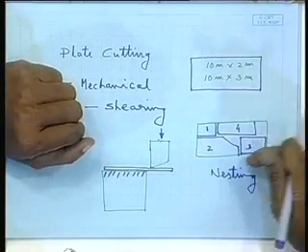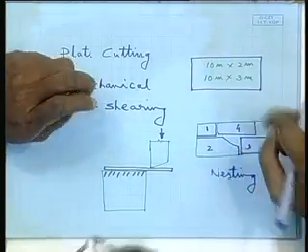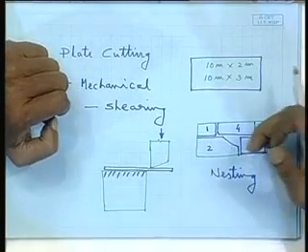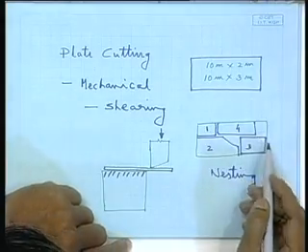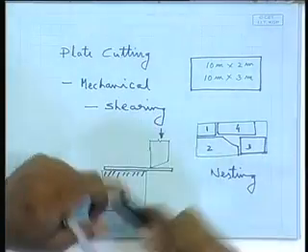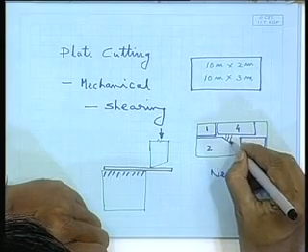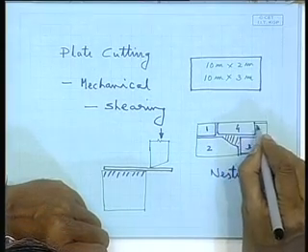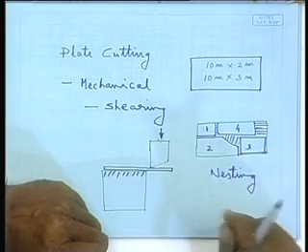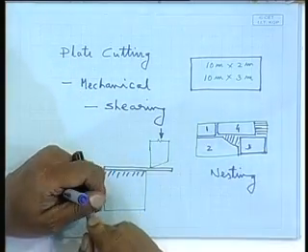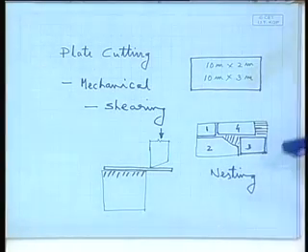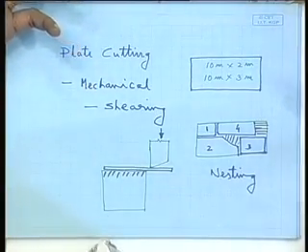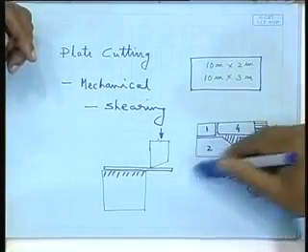So, once you have that, you can do this so-called nesting, such that you can make as much utilization of the plate as possible, because the way I have drawn here, this part will remain as so-called scrap, is it not. This shaded part is becoming scrap, will not be used for anything, it will be thrown out. But the objective should be to minimize this scrap, because there is wastage. So, that is what nesting is.